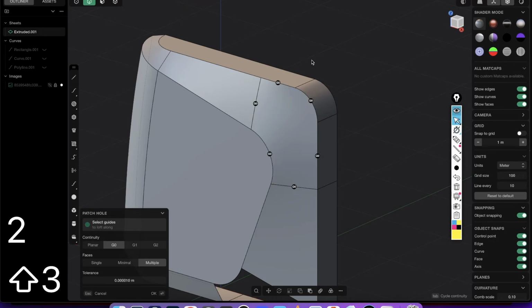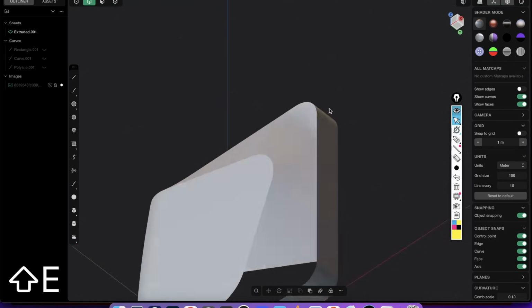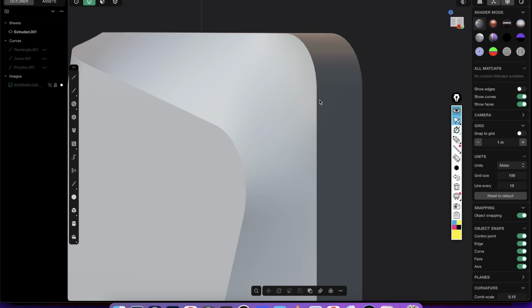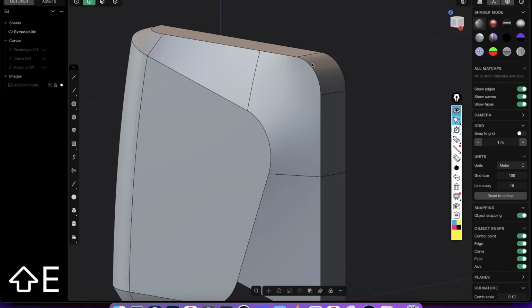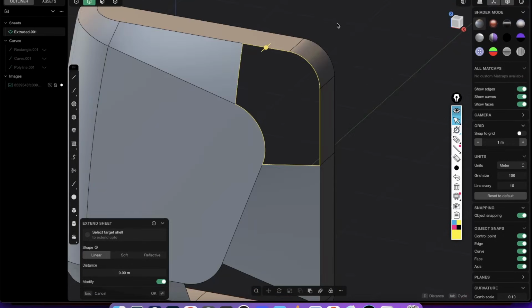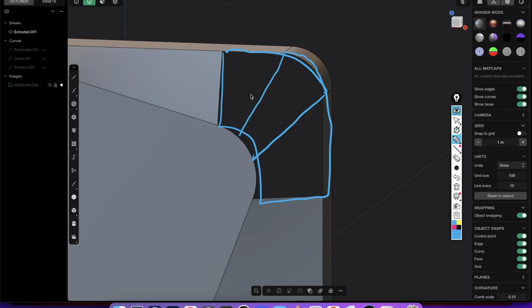And again, you can just try to patch it. And with G1 and G1. And you see this looks already better, but we still have this massive curve and now it's even stronger. And a very simple beginner way to do that is, so go delete this face and we have to add here 2 guiding lines. So again, here we have this fillet, right? So we have to add here a line and here a line, which will be straight. And then we will again patch it and